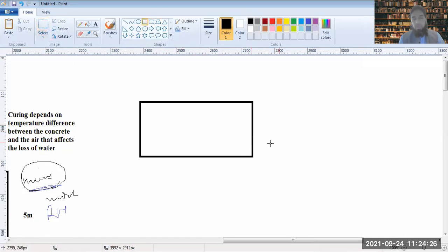What we plan to do there is to put in heaters with auto stop, such that once the temperature of the water rises above 30 degrees Celsius, they will be shut down. So we'll be having controlled research on the effects of curing at around 30 degrees Celsius.